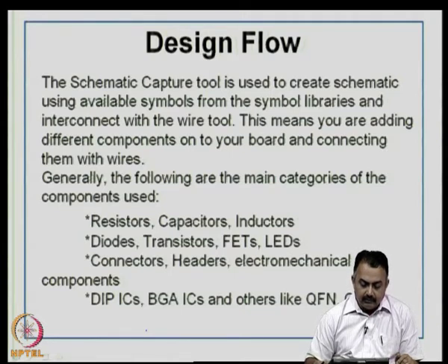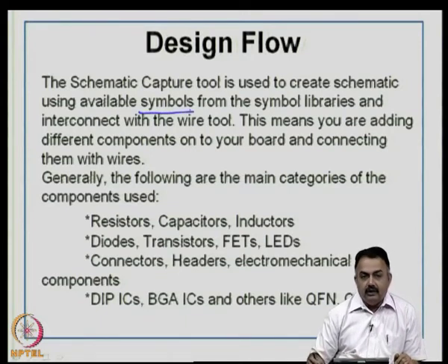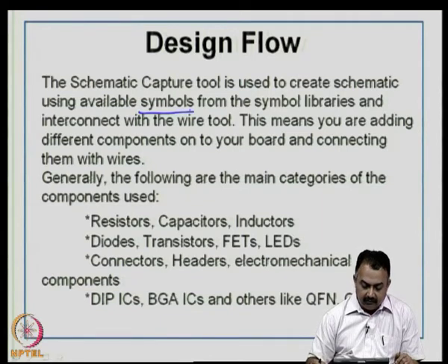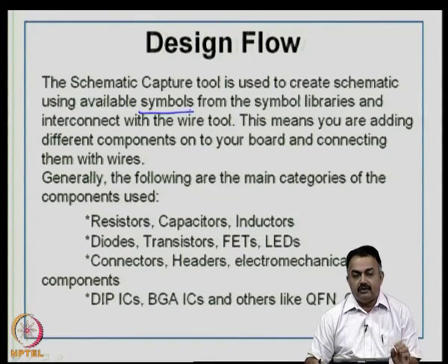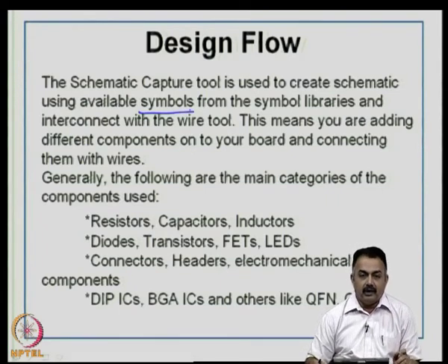The schematic capture tool is used to create a schematic diagram using available symbols. So, in a schematic capture tool, you are worried about bringing symbols from the libraries. So, you will use available symbols from the symbol libraries and interconnect them with the wiring tool. Once you bring a symbol, and you have put all the symbols for that particular diagram, the next job is to interconnect them. This means you are adding different components onto your board and connecting them with wires.